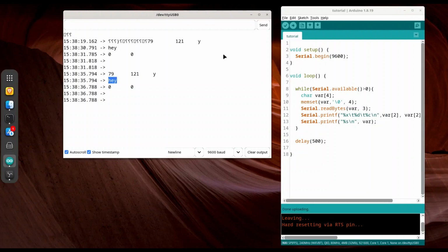And just to remind you, I told you that this is the most useful way to communicate with microcontrollers. But I didn't tell you why exactly. Because you want to keep your communication and everything you are doing with your microcontrollers as simple as possible. Means while you are communicating, you want to use the least possible number of bytes. And now let me try to explain how to do that in the best possible way. Let's say that you have a temperature and motion sensor, and let's say that you have 2 or even better 4 pins that you want to operate with. You could send one number that is going to define what you actually want to do.